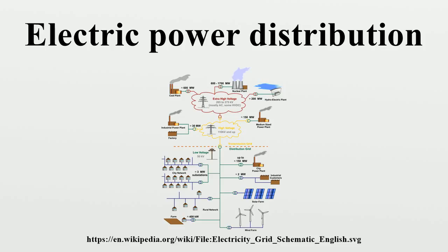Variations. North American and European power distribution systems differ in that North American systems tend to have a greater number of low-voltage step-down transformers located close to customers' premises. For example, in the US a pole-mounted transformer in a suburban setting may supply 7 to 11 houses, whereas in the UK a typical urban or suburban low-voltage substation would normally be rated between 315 kVA and 1 MVA and supply a whole neighborhood. This is because the higher domestic voltage used in Europe may be carried over a greater distance with acceptable power loss.